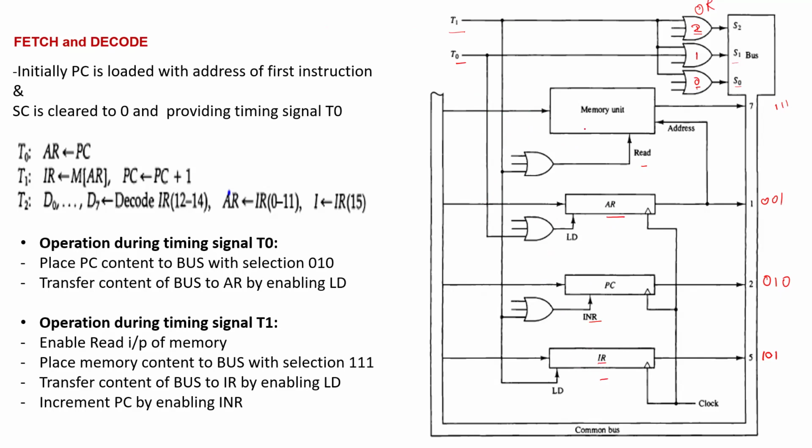So now how is this operation going to happen? The address register is going to communicate only with the memory, as you can see here clearly. Now, when this address will be transferred, or when the address register will be loaded, or when there will be an increment in the program counter, all of this is decided during the timing cycle. We have already seen about time and control.